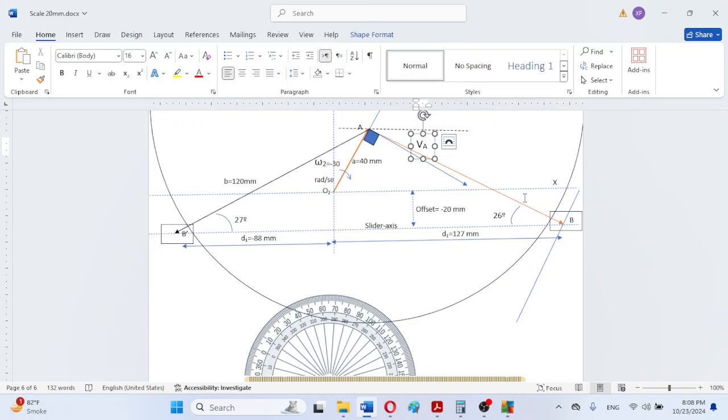There is a technique or method: if we split the motion of the connecting rod into simultaneous translation with the crank point A and then its rotation about point A, but that concept will be explained later. So at this stage we are not concerned with the exact orientation prior to the velocity triangle.